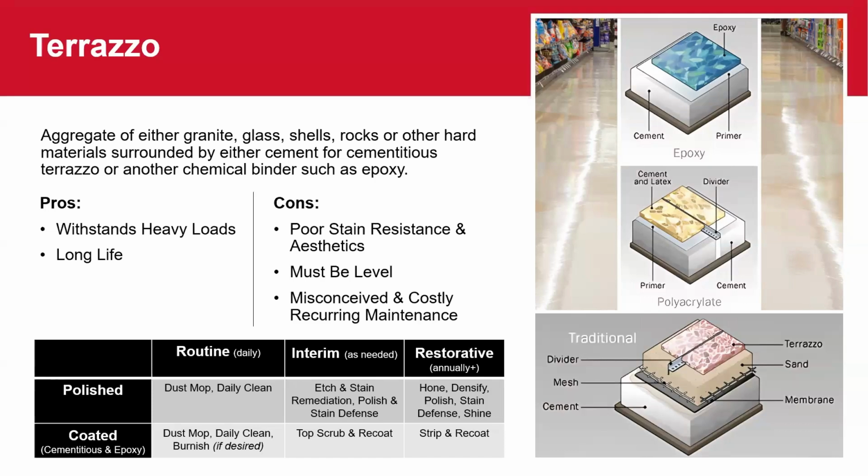They must be level. The concrete floor must be level underneath, and these floors can be very expensive to maintain. If the terrazzo is cementitious, it can be polished just like a concrete floor. So you can hone and polish: hone, densify, polish, and put a stain guard on,